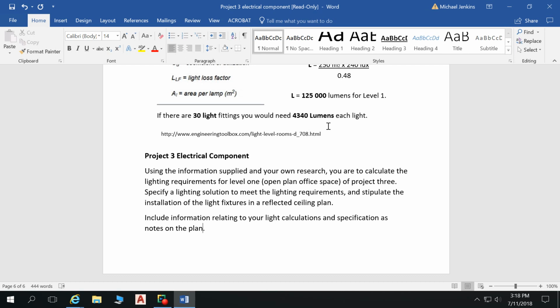That's not what we want to see. We want to see that underside. So you imagine there are mirrors on the floor, that you're actually looking at that mirrored version. So that reflected ceiling plan has exactly the same shape and outline and orientation as all your other plans, but it shows things from underneath. Does that make perfect sense?